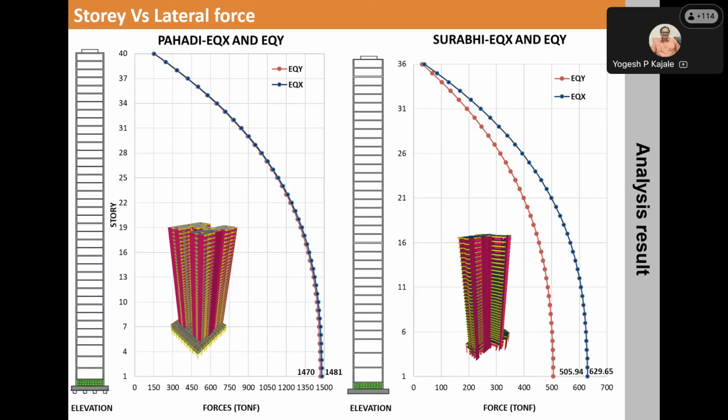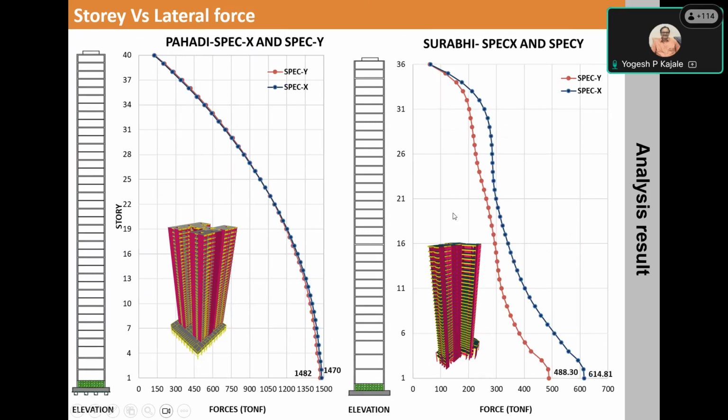The seismic analysis was completed, and the base shear distribution was also plotted. Particularly for the Y-shaped building, you will see that the base shear distribution is not uniform or particularly parabolic in nature, because the mode shape changes in the Y-shaped building.